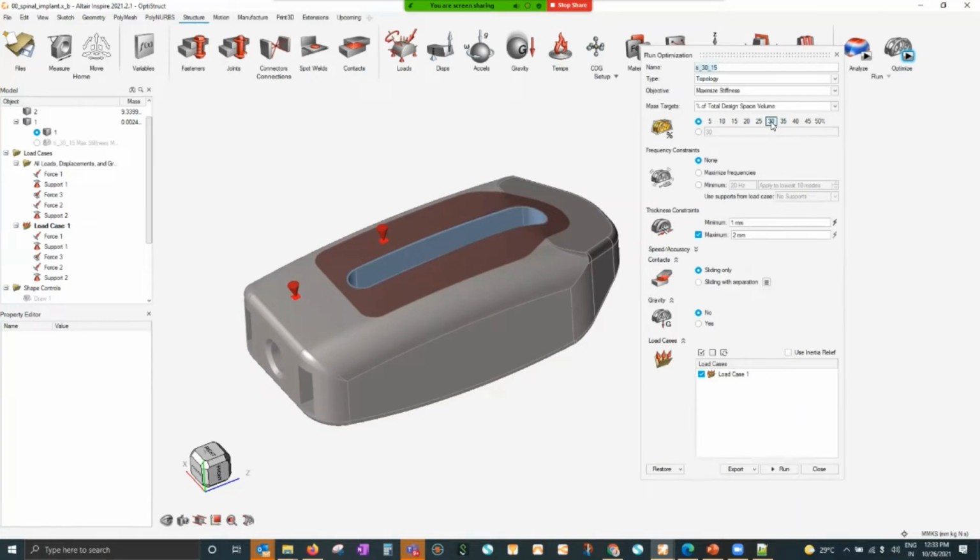We know that we have selected the best possible 30% where it contributes the maximum. But then 30% itself may not be sufficient to withstand this load. In such a case, you would see a higher stress and displacement, right? So that kind of confirmation, especially when you are into a minimize stiffness kind of objective function.